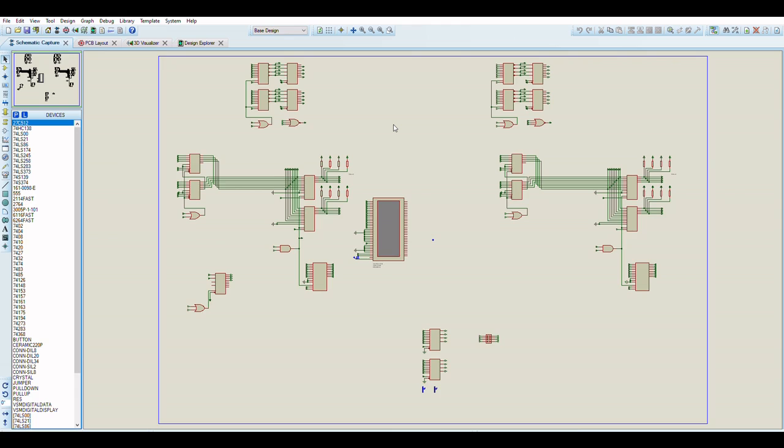And while one is outputting calculated pixels through to the output pixel header down here via these two demultiplexers, as you can see, depending on whether or not it's an odd or even scan line, it will choose the input from the left here and then output it to the right here, which then goes to the output pixel header.